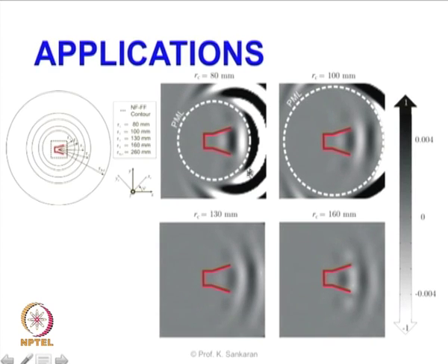The PML layer is starting from here as we discussed, and what you see here is the absorbed field values. So here it is dark circle because the fields are getting absorbed. These are the layers in which the losses are there, and as I increase the radius of curvature I am going larger and larger.